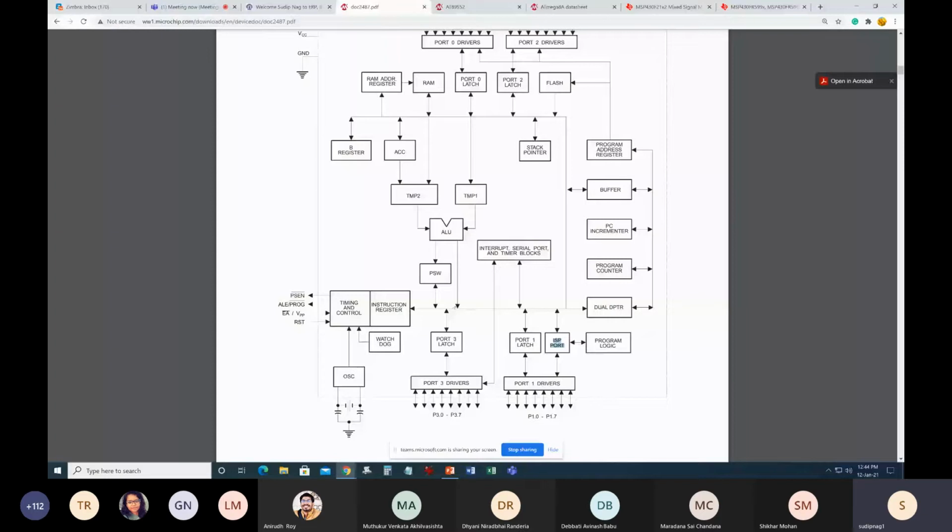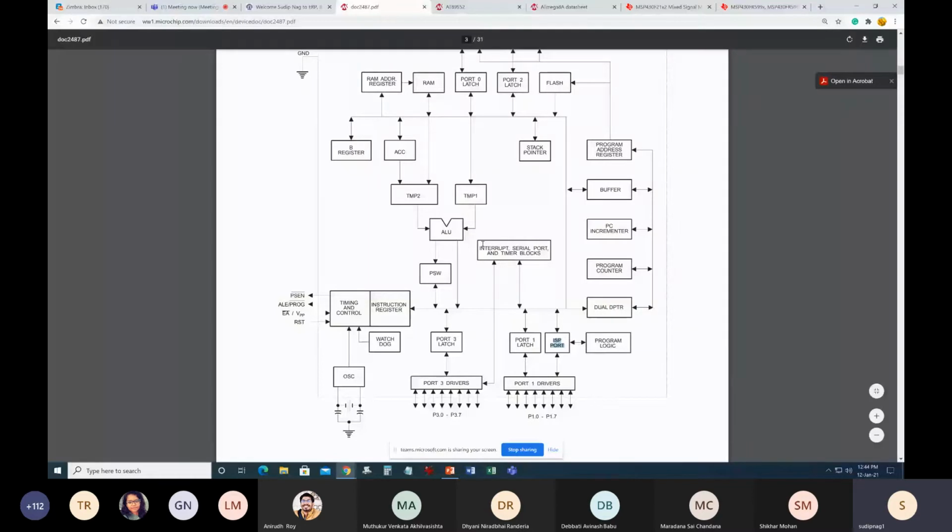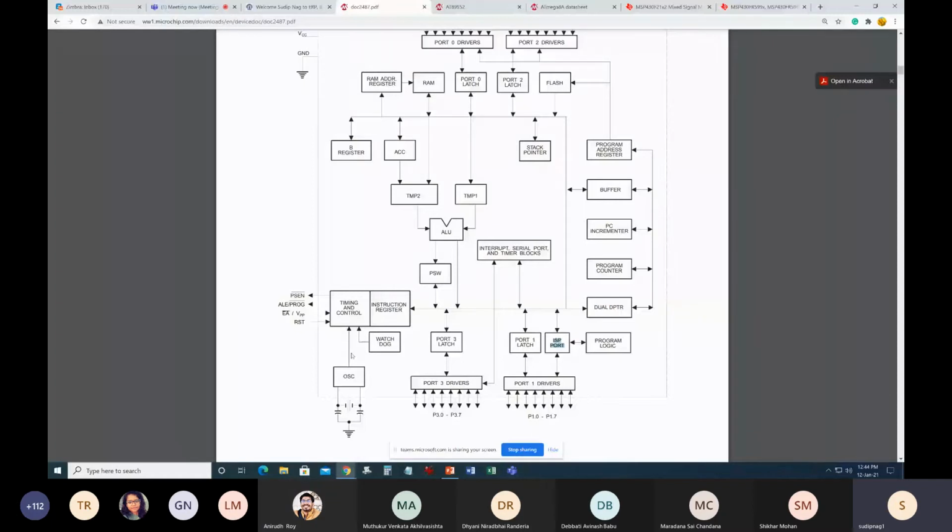There are two types of data input, if you want to learn at this point in brief. One is interrupt based data transfer, the other one is polling based data transfer. So you can do software polling, or you can just wait for the interrupt. Whenever an interrupt comes, this clock is always available to the interrupt if you enable the interrupt. So your time resolution is 1 clock cycle at least. That is the minimum time that must be required to identify an interrupt.